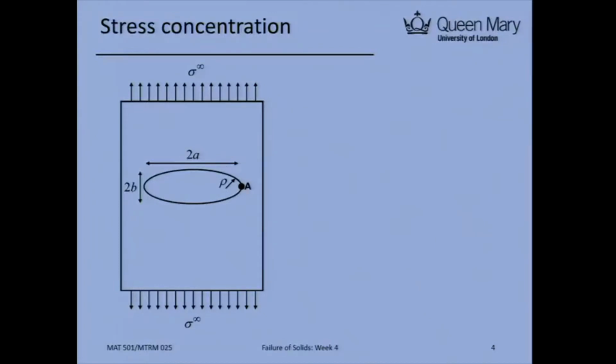Here you are looking at an elliptical hole, with a width of 2a, a height of 2b, and a radius of rho. You are applying a uniaxial loading remotely. By remotely, I mean the hole is far away from the loading point, so the stress will eventually be very uniform along here.